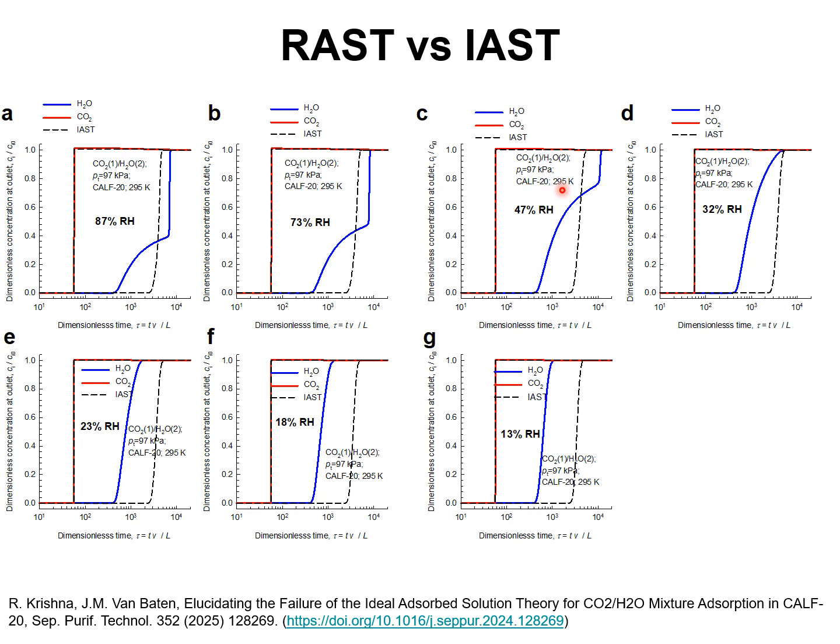I invite you to recall that in the actual experiments, during the initial transient for a very short period of time, there is a sharp temperature rise, whereas for a large proportion of the breakthrough time interval, isothermal conditions are more or less prevalent in the breakthrough experiments.